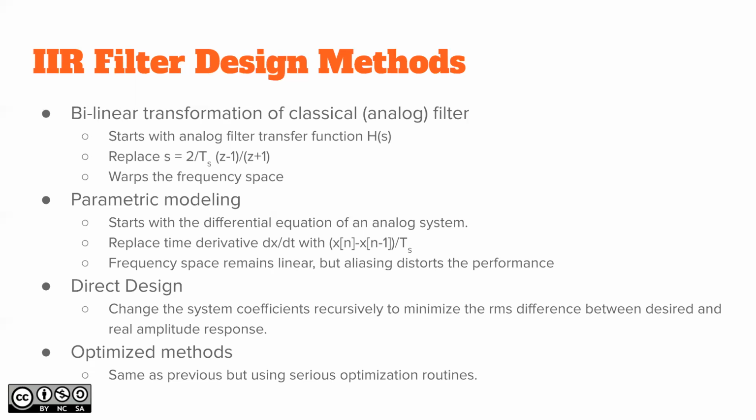So those are the digital filter designs of the old-fashioned Butterworth, Chebyshev, elliptic, Bessel kind of filters. It starts from the analog transfer function and uses this bilinear transformation.